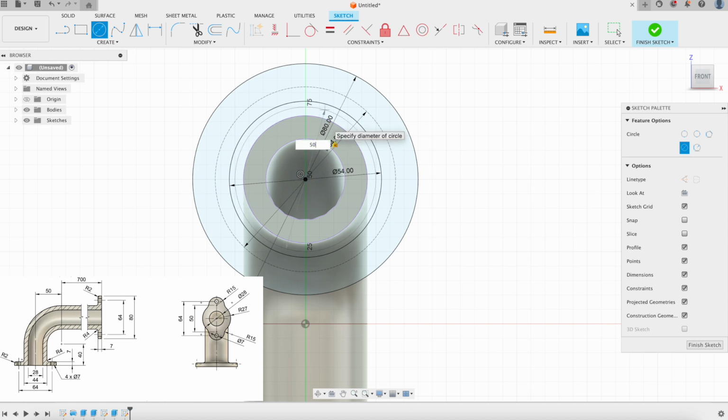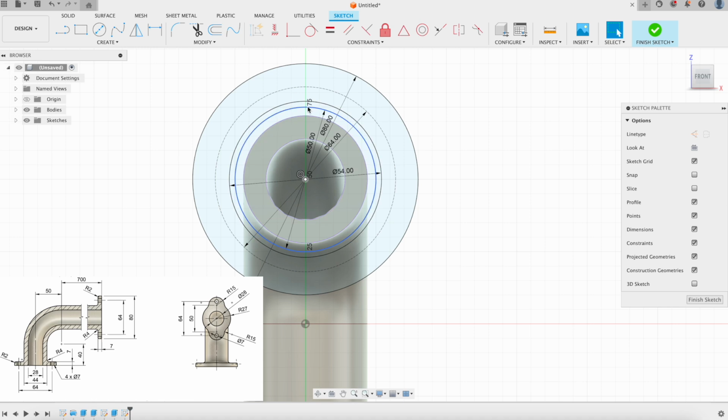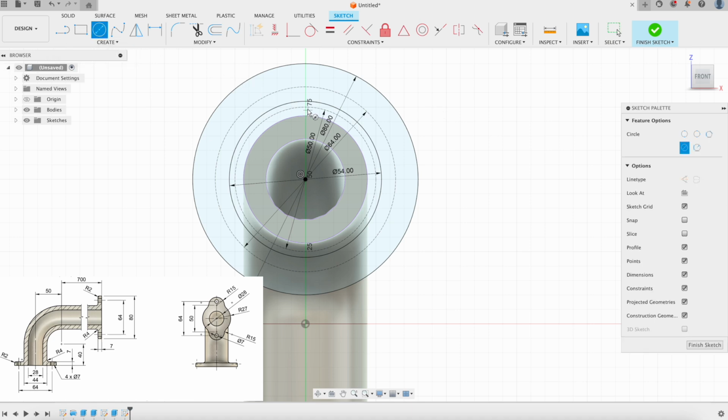This one only being a diameter of 50 millimeters, and this one is also a construction line. Okay, and from there, we could go in and add all of our missing circles now. So along this top portion, we have our radius of 15, so diameter of 30, and you'll notice that it falls perfectly tangent with this circle already. So we could go ahead and click OK.